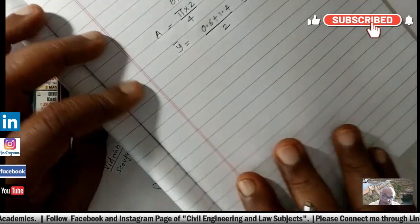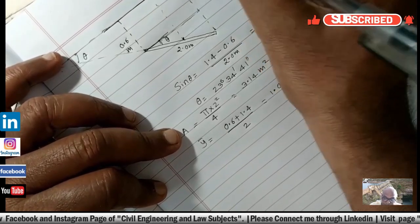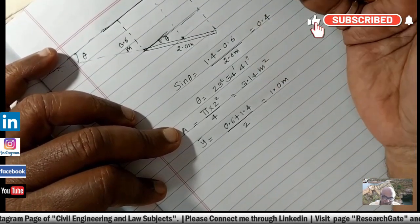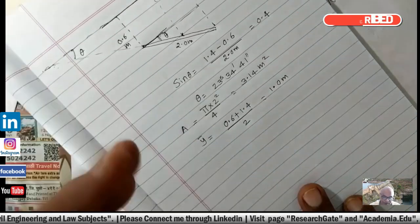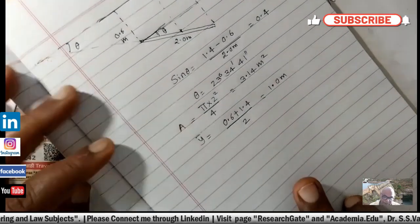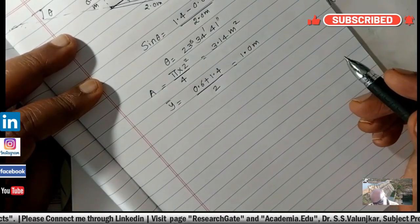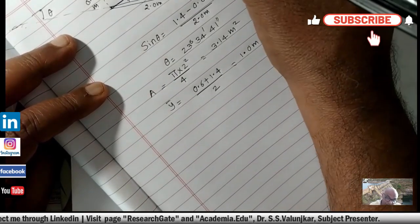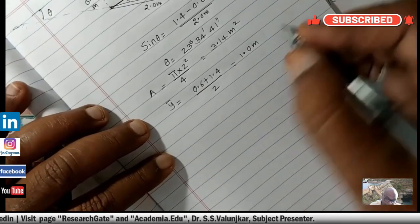Now here we have to take caution: specific gravity 0.8 is given. Not necessarily is the free surface always water. In some other branches, like mechanical or chemical engineering, this liquid may be different, so the specific weight also differs. So we have to take the specific weight of that liquid related to the specific gravity 0.8.